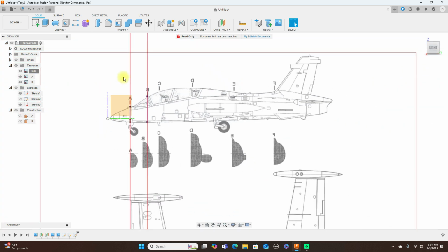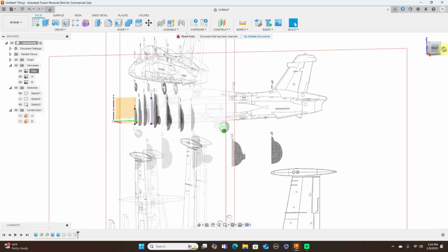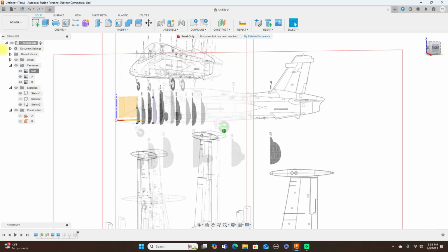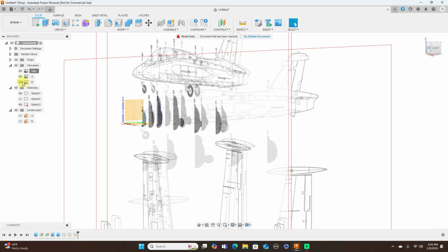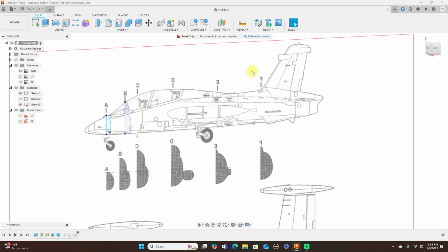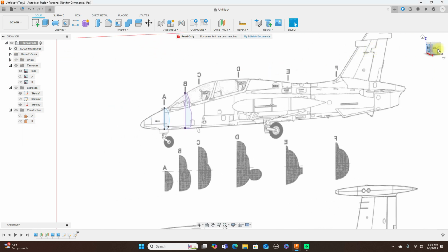And then next, doing an offset plane, another important command. And we put those planes in A and B. And then sketching. After we got those planes in there, then insert a canvas onto those planes and then calibrate those. So far we haven't even used 5 commands. So there's not a whole lot of commands that you really, really need to know. Okay.